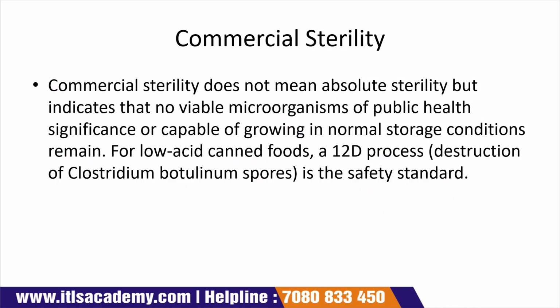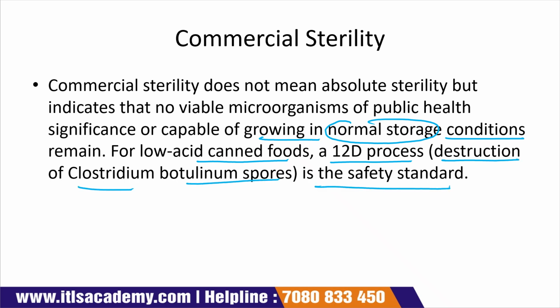Commercial sterility does not mean absolute sterility, but indicates that no viable microorganisms of public health significance, or capable of growing in normal storage conditions, remain. For low acid canned food, a 12D process, that is destruction of Clostridium botulinum spores, is the safety standard.